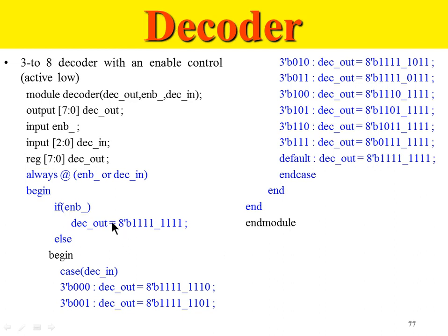That's why you should use non-blocking assignments everywhere as far as design goes. Design means anything that gets implemented on a chip and finally on a board. For designs, use non-blocking everywhere. Test benches are only meant for simulation purposes, so for test benches you're free to use blocking assignments. No problem.